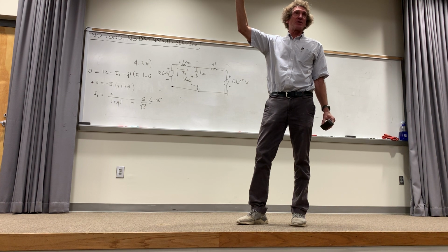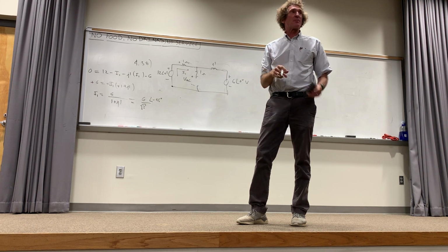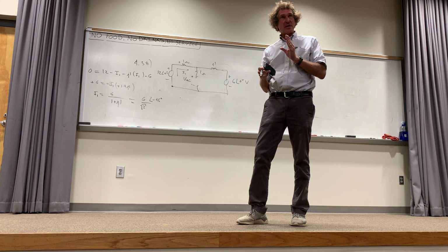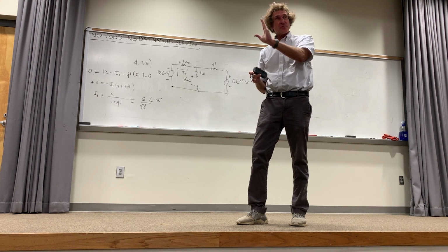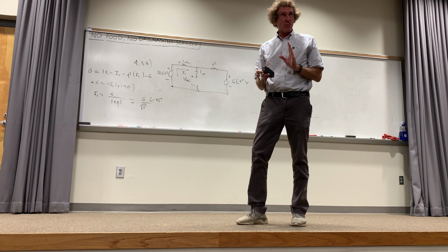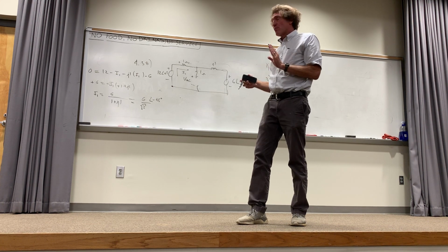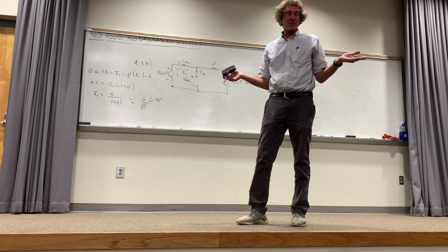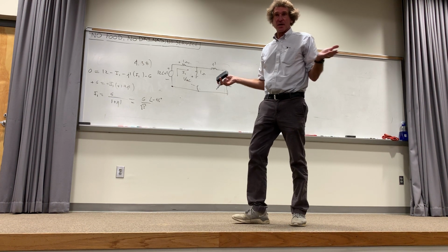If you have a plus jb, the magnitude of that number is the square root of a squared plus b squared. The angle is an inverse tan of the imaginary coefficient divided by the real coefficient. That's it. Well, I know if I have 1 j1, the inverse tan of that is 45 degrees, just from experience, not tricks, okay? That's how I got that.